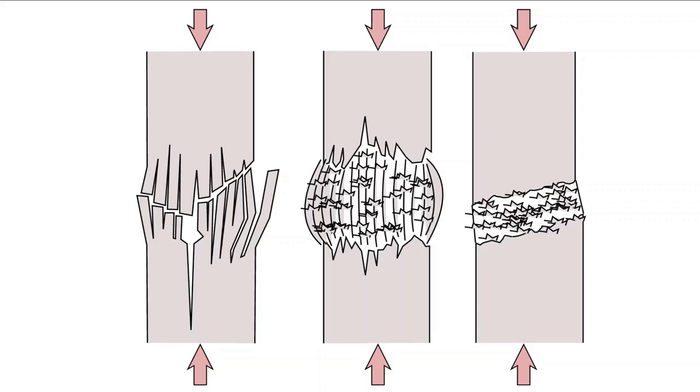Fiber-reinforced composites loaded in compression present a wide array of potential failure modes, with a few notable ones depicted here. By and large, if there is a common failure mode, it is that the matrix is overloaded at first and not able to support the fibers effectively, which in turn causes the fibers to buckle. The way in which this can manifest is according to these three mechanisms.